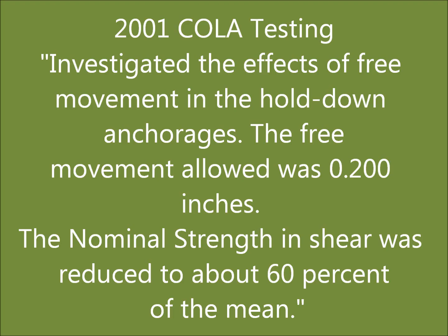In 2001, the city of Los Angeles ran a series of tests on shear walls. Its purpose was investigating the effects of free movement on hold-down anchorages. The free movement allowed was 200 thousandths of an inch. In the result of this test, the nominal shear load was reduced to about 60% of the mean.